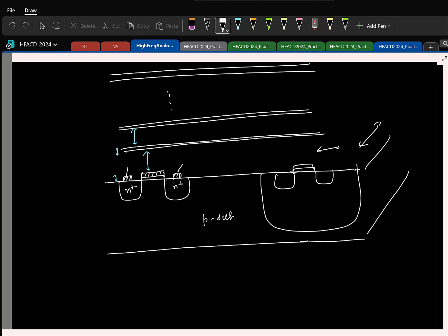And if you draw it, it's your first year engineering drawing. If I draw the top view, I'll have for a MOSFET, this is the polysilicon, and then this is your source and drain. So this is the length of the MOSFET. This is the width. Great. So next, in addition to MOSFETs, what other components do we need for making circuits?